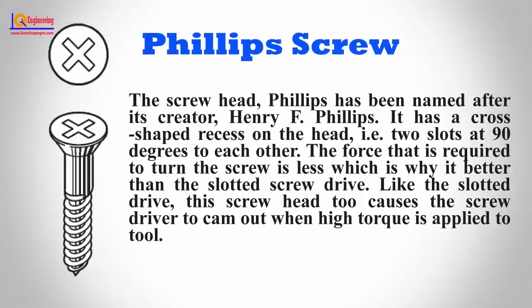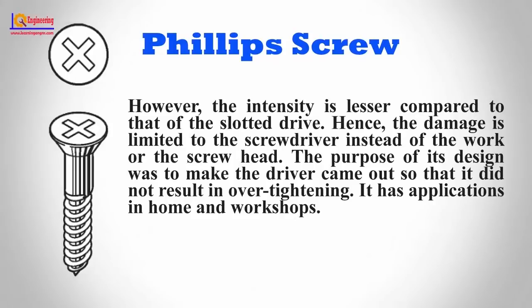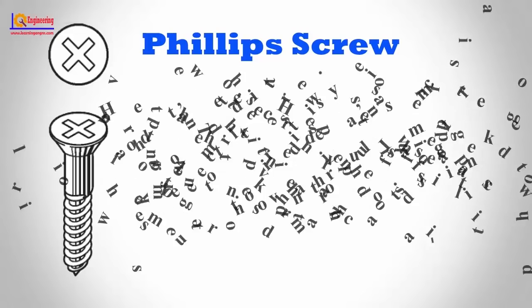Like the slotted drive, this screw head too causes the screwdriver to come out when high torque is applied to the tool. However, the intensity is lesser compared to that of the slotted drive. Hence, the damage is limited to the screwdriver instead of the work or the screw head. The purpose of its design was to make the driver come out so that it did not result in over-tightening. It has applications in home and workshops.